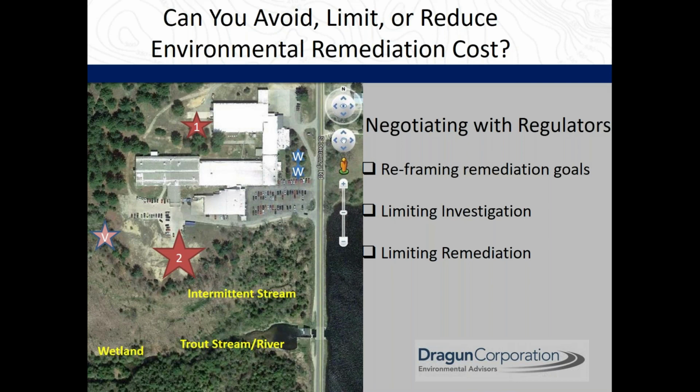of the project. And RCRA corrective actions at this time in the mid-90s typically involved nature and extent definition to non-detect for contaminants, and the US EPA was certainly driving towards this non-detect delineation. So if we were to leave contaminants in soil or groundwater, that usually required undertaking a full human health risk assessment for the site under RCRA. In this situation, as I mentioned, Michigan had recently promulgated risk-based criteria that included industrial scenarios.